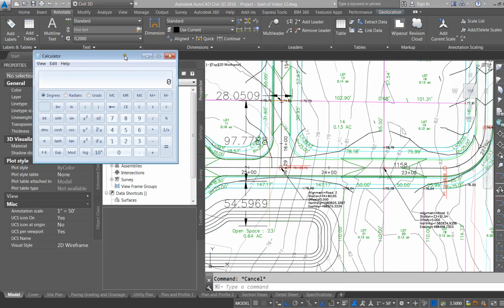We'll get that open while we're working. And the first thing I have, if I start upstream at a 72 and I'm going downstream at 0.0025% times that 28 feet, that gives me the invert here. So I'm going to say 70, not 72. 70 minus parentheses, 0.0025, that's the slope of the pipe, times 28 feet. So the invert here is going to be 69.93.